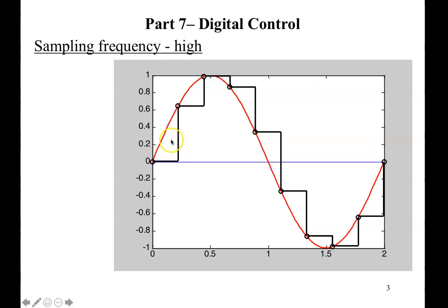And then if you look at it closely, if I do an average of the black line, that's about half an interval. So there's a delay of half an interval. Nine samples, one interval will give you 40 degrees, but half an interval will give 20 degrees. So because of this sampling zero order hold business, you get a delay of 20 degrees. Negative 20 degrees, that means you lose 20 degrees in your phase margin.